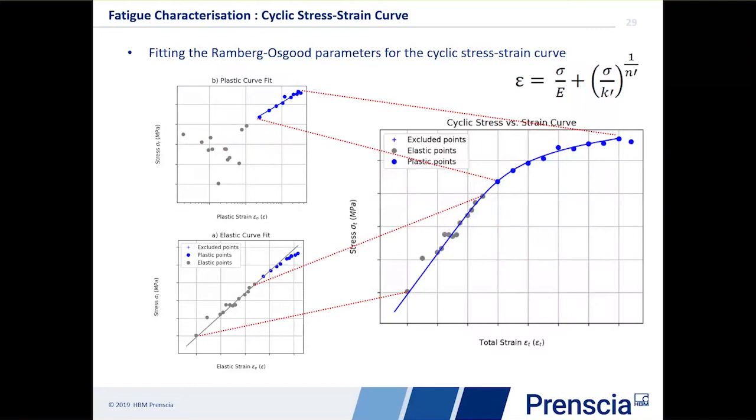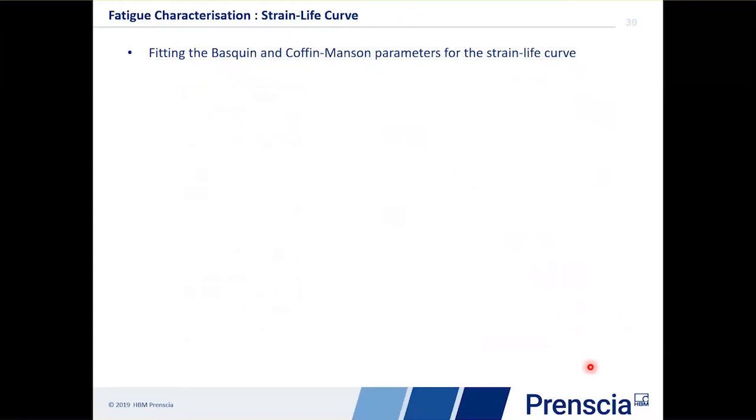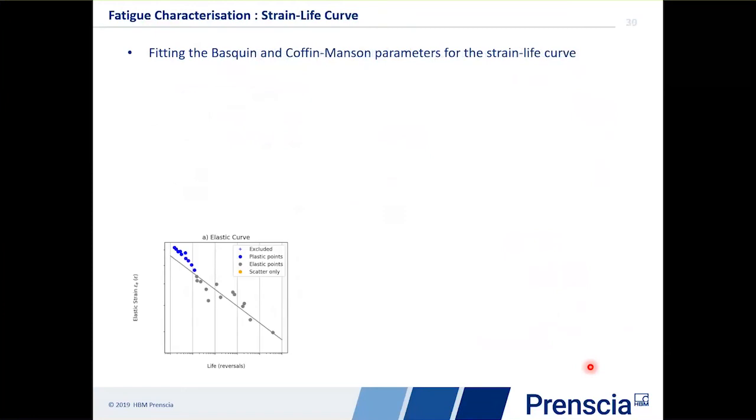We use a similar approach when it comes to fatigue as well, for fitting the Basquin-Coffin-Manson parameters. So here, again, we've taken the elastic strains and we've plotted versus life.